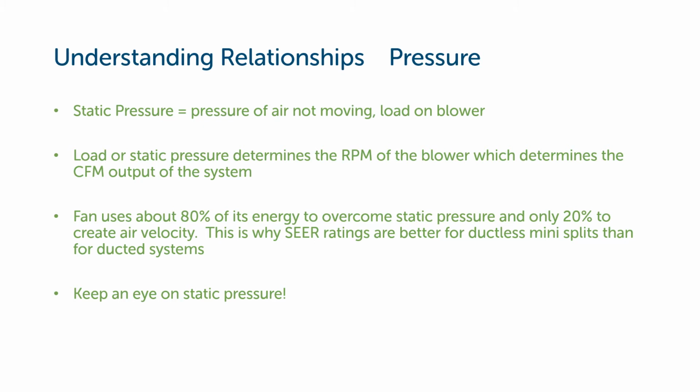And this is why when you look at the SEER ratings on heat pumps, the ductless mini splits have better SEER ratings because they don't need to push against the duct system. They don't need to push against the static pressure within a duct system. So we don't have all of that fan energy being wasted or being used to overcome the static pressure in the system.